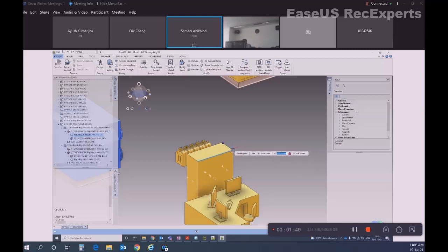I want to fix the easting with this, or you can fix easting with this. You can see the blue dot, the actual snap is the blue dot which you see behind the square box. So easting will be picked from this point, but northing is locked. So it is telling the coordinate of this point.